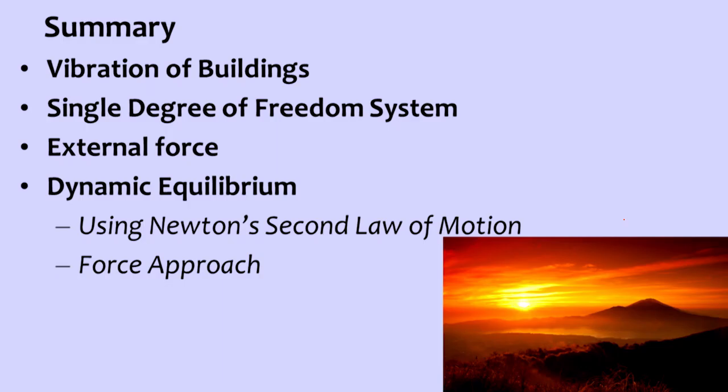In summary, what we have studied in this module is vibrations of buildings, what a single degree of freedom system is, how the external force is applied, and how to formulate the dynamic equilibrium equation. We formulated it in two methods. One is using Newton's second law of motion, and the second is the force approach, that is, D'Alembert's principle. Thank you.